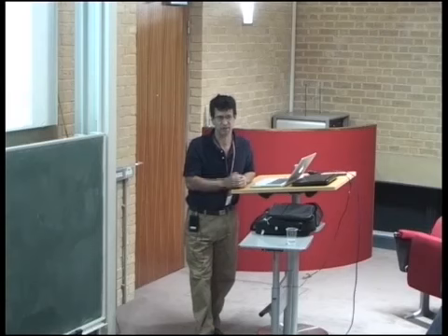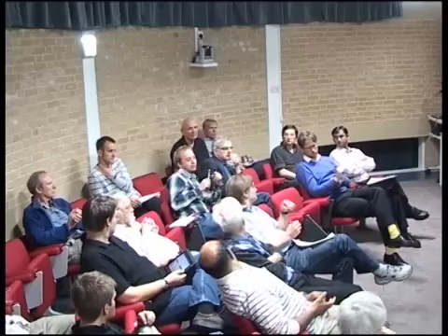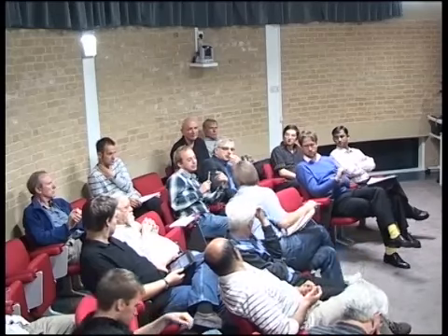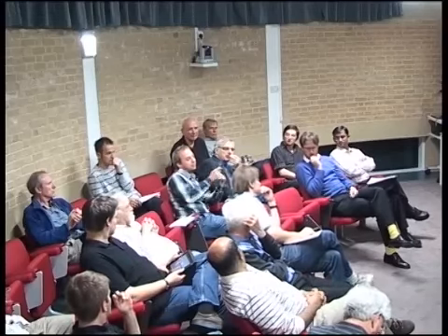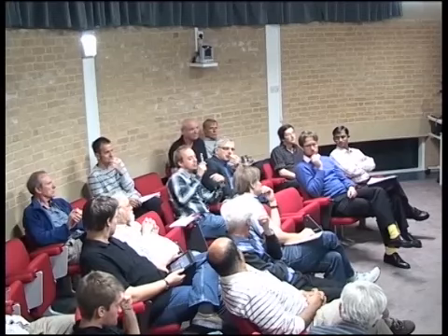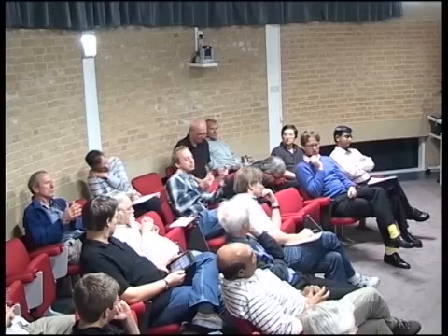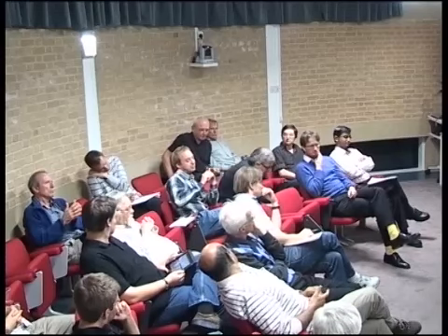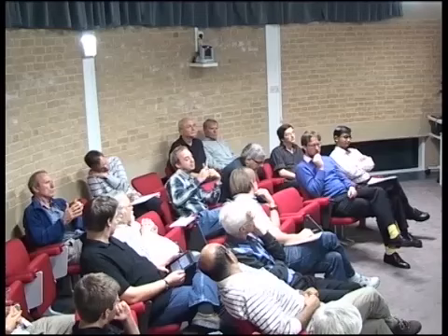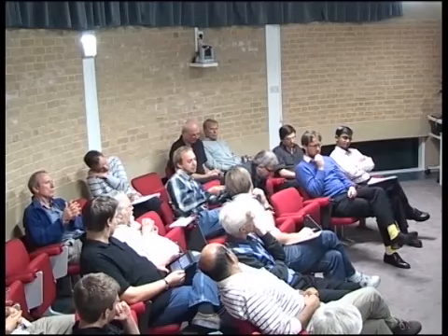It's quite convoluted. Bruno, I just have to say that you can use whatever explicit real-time method you want, but with the method that Konstantinos could propose, you lose the order accuracy at the buffer regions, and you have a maximum of second order. So if you use a classical RK4 method, globally you will only have second order of accuracy, because you lose it at the buffer regions. And secondly, for DG methods and for finite volumes, you need these buffer regions to be as large as the number of stages in your explicit base method.